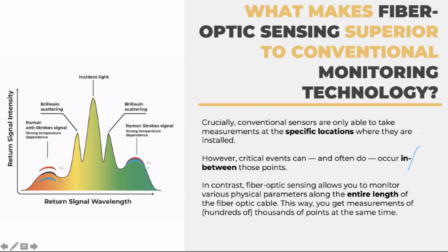Advantage of that method is that we must do nothing. We just buy traditional fiber optics telecommunication cable, put it, and then use a special kind of interrogator with special software to analyze the reflected signal and then make conclusions. Actually, when we work with Brillouin and Raman reflected technology, we see the spectrum picture.